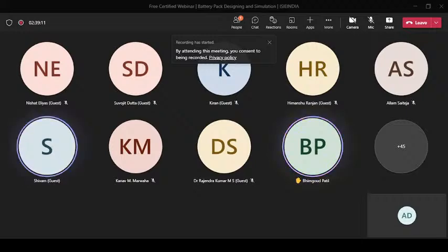But sir, as I'm using them in parallel, let's say the 10 Ah will discharge and be cut off, out of the system indirectly. And that 20 Ah has another 10 Ah capacity that can still stretch. That will still remain there, but to use that, you have to cut off the completely discharged 10 Ah battery pack from your vehicle. Why, sir? Because I have a separate BMS for the 10 Ah and a separate one for the 20 Ah. Does current go in? I don't think it will go in the BMS from one cell to the other.